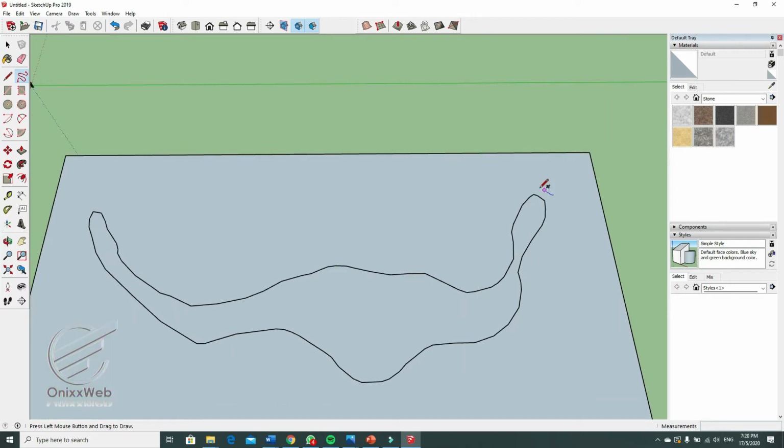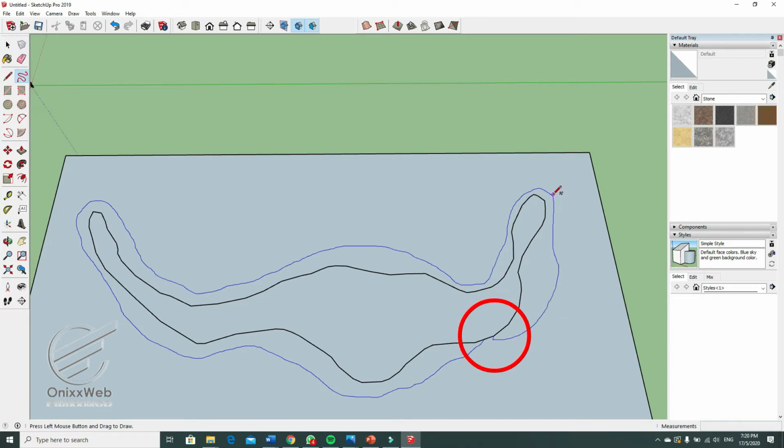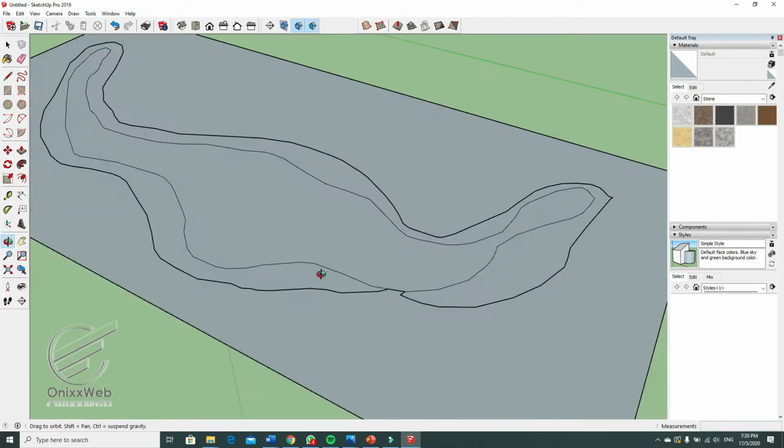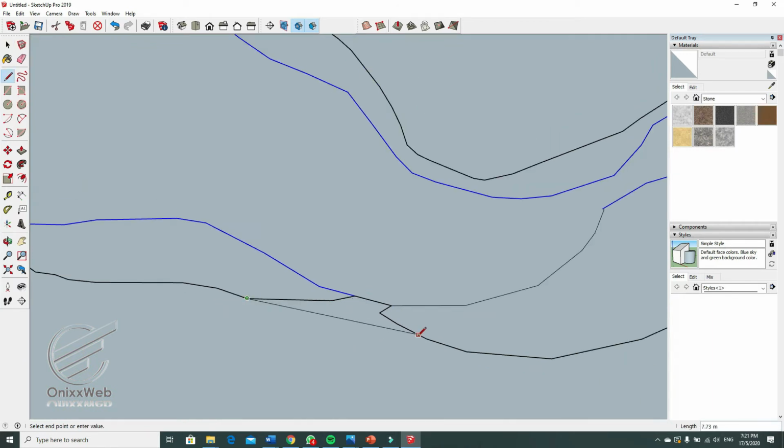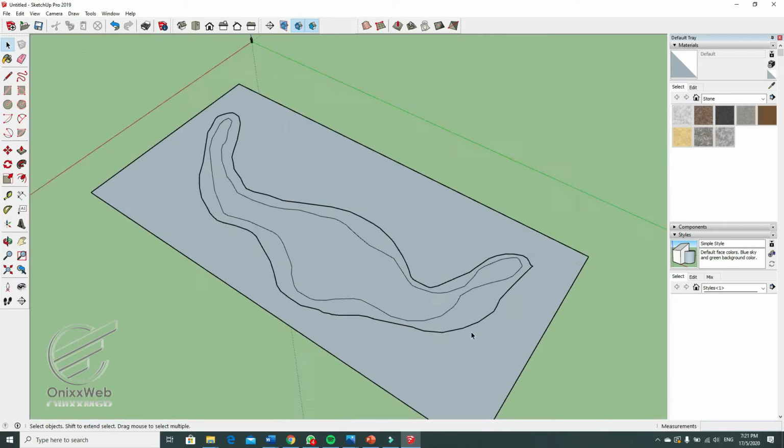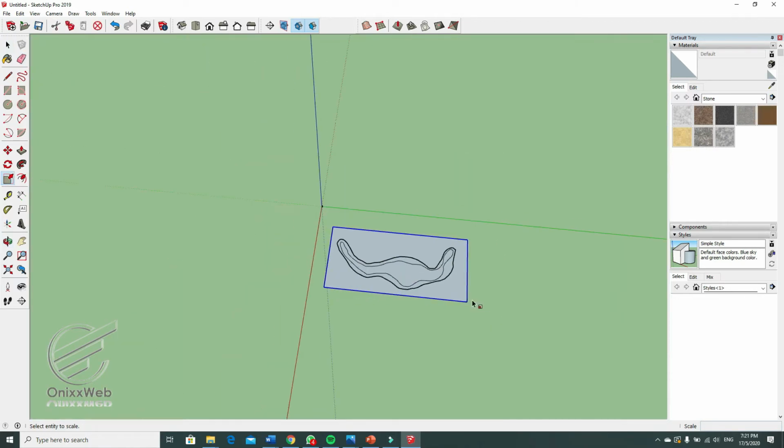Click a distance from the existing contour line we created to create a second contour line. Be sure not to cross the lines that you created when drawing the second contour line. If you accidentally cross the line, erase it and create another line to connect it. One of the peak locations of our terrain is outlined by these two contour lines.